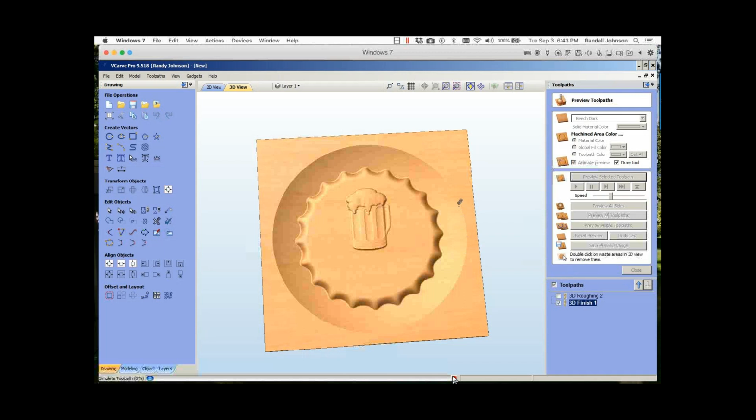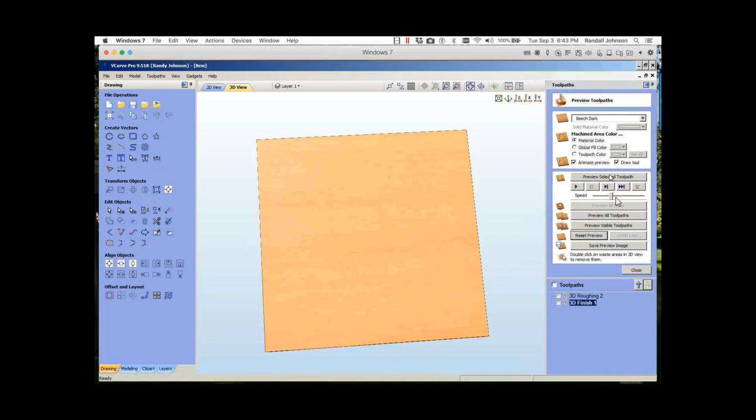Okay, it's starting at the edge, kind of like at the edge of a shore, very shallow, and it's going deeper and deeper. So at the shallow point, it's putting very little stress on the 1/8 inch router bit. But once you get into the deeper material, because we're only taking off about 10 thousandths of an inch, that also is putting very little stress on the router bit.